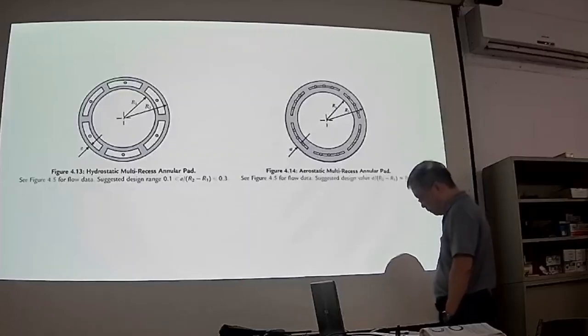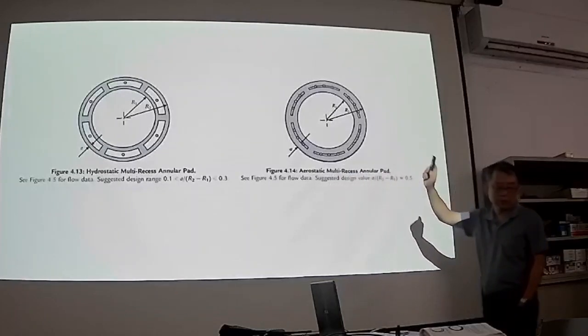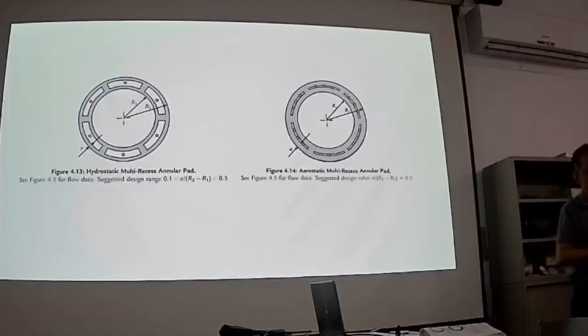And for air bearings, we tend to use them without any recess. Instead, if you still want to increase your stiffness or load capacity, there's another way.